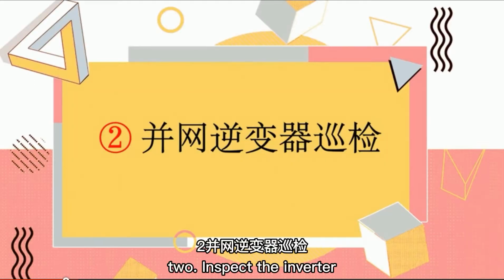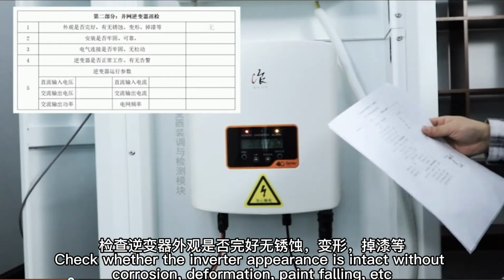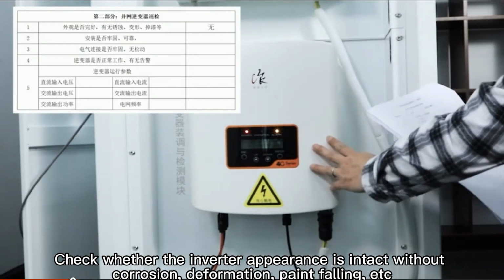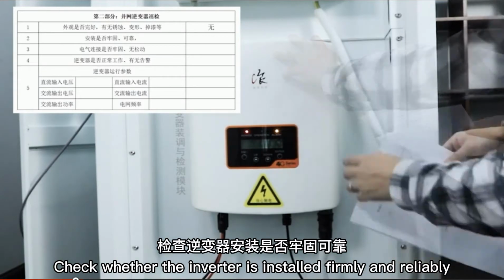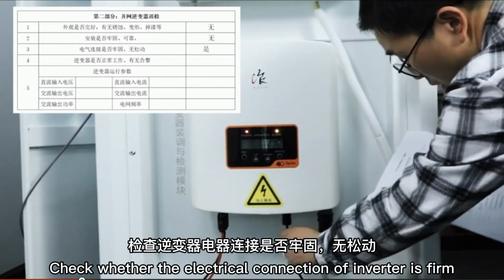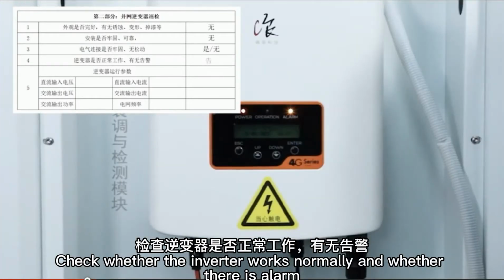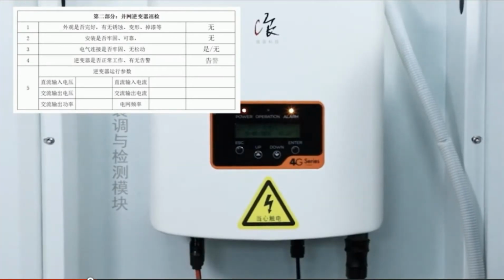2. Inspect the inverter. Check whether the inverter appearance is intact without corrosion, deformation, paint falling, etc. Check whether the inverter is installed firmly and reliably. Check whether the electrical connection of the inverter is firm. Check whether the inverter works normally and whether there is an alarm.